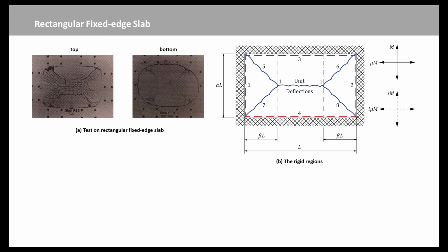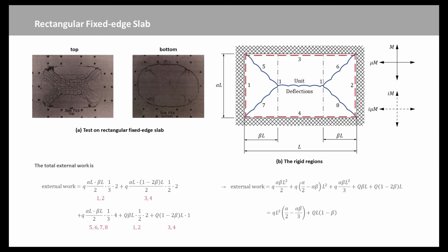This means that some complicated expressions would be needed to define the moment about the axis along the yield lines and the rotation of the yield lines. The vector method gives the internal work without too much trouble. Once the work equation has been found, it is necessary to find the critical value of beta. The loading on the slab is assumed to be ultimate dead load q per unit area, and line load Q per unit length along the center line.